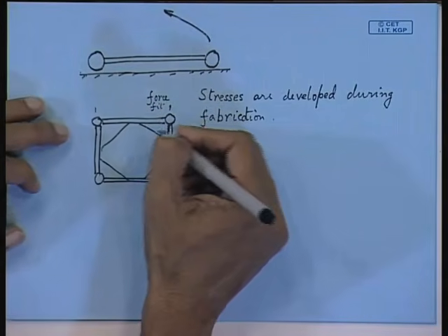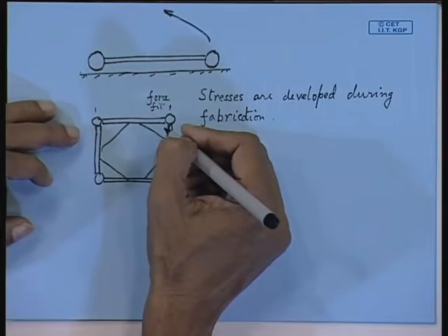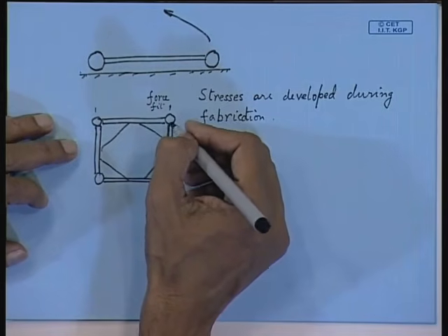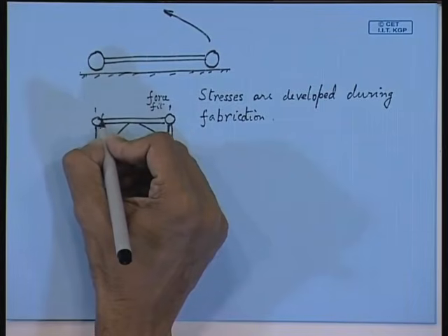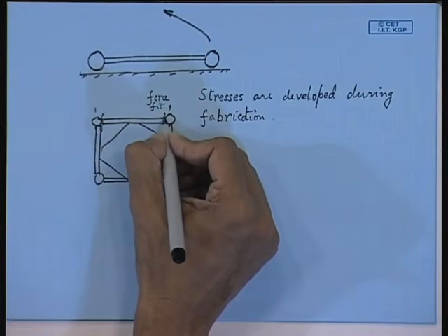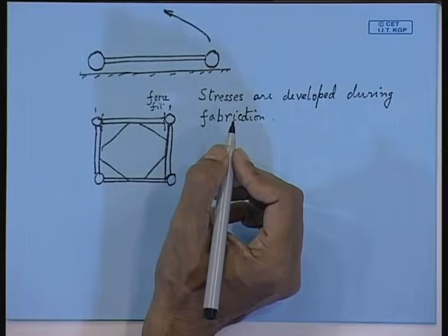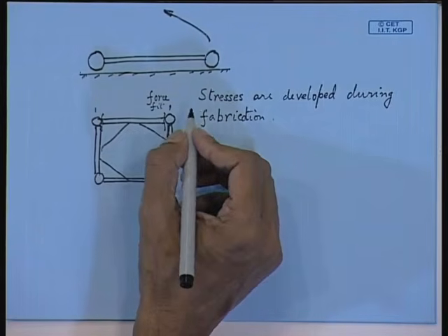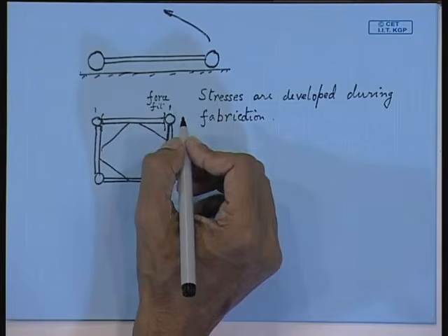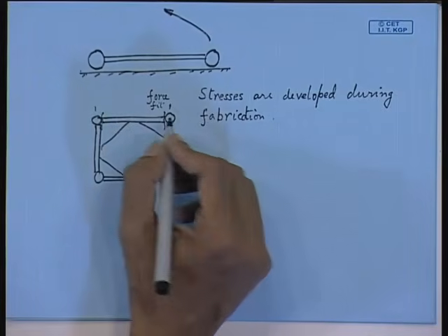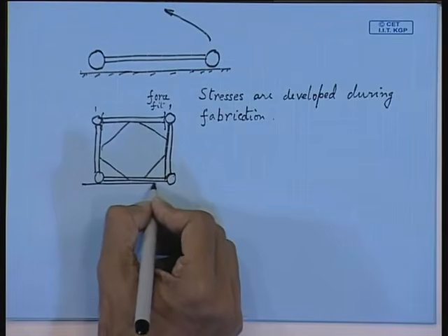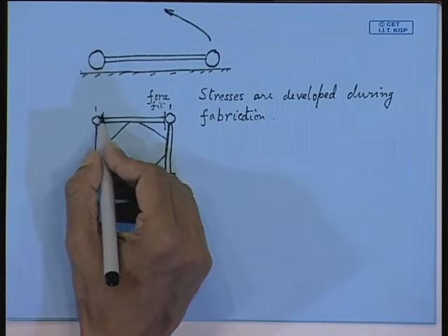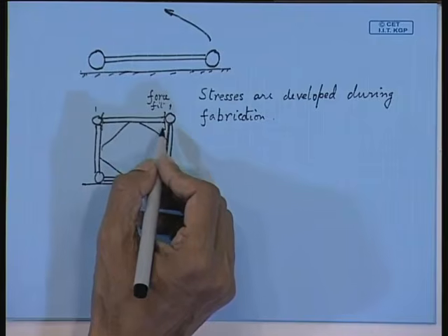You try to force fit one panel with another panel. So, what will happen? A lot of stresses will develop at the junction between the columns and the bracing members, and when the jacket is released or when it is being transported to the launch barge, you will find cracks developing.